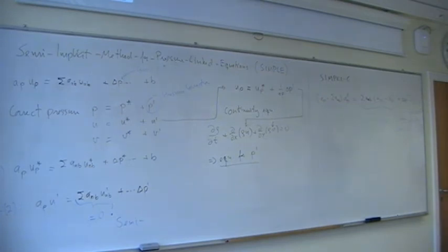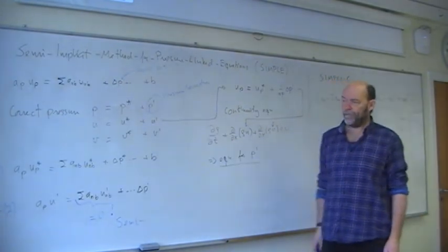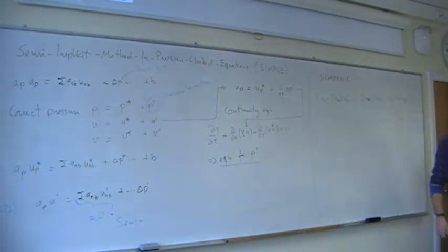This is the essence of the finite volume methods. This is hard to avoid. Nowadays you also have more sophisticated methods, some PISO algorithms using the predictor-corrector idea as well, and then some additional correction terms, but I would say the heart of the method is here anyway, so of course you have variants of it. That's okay?